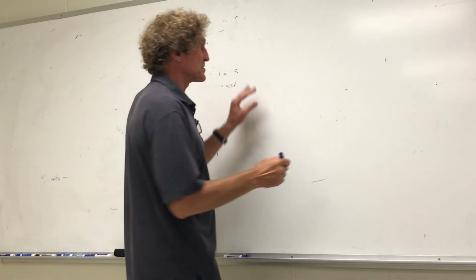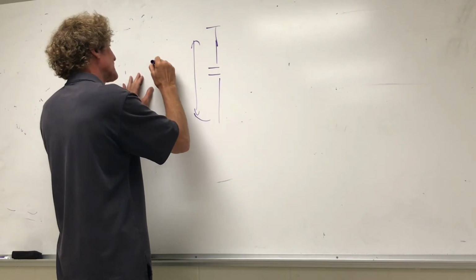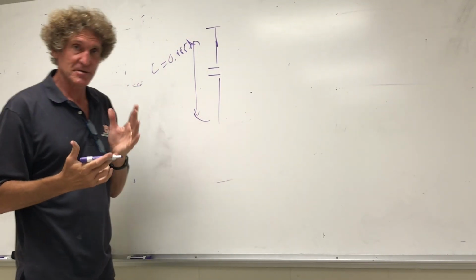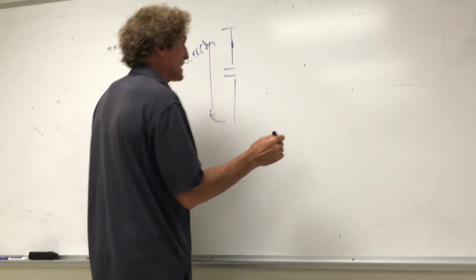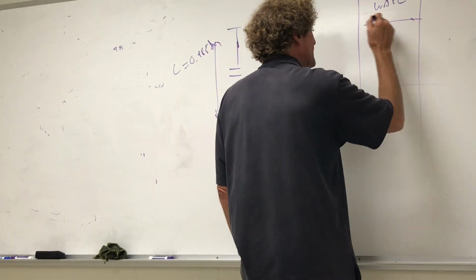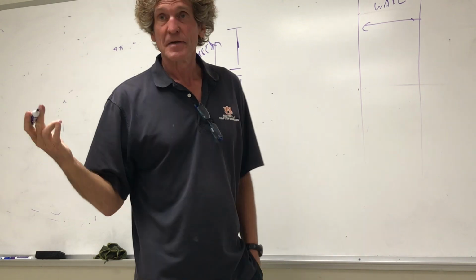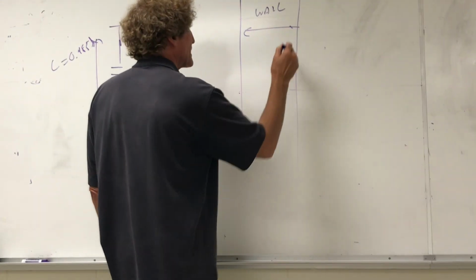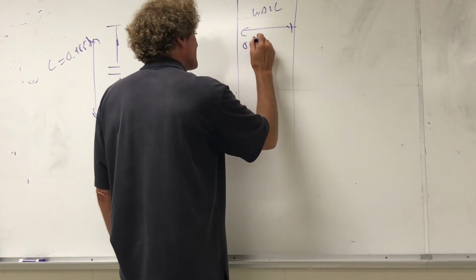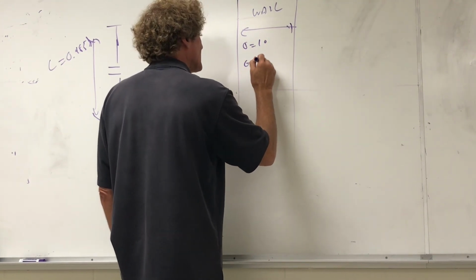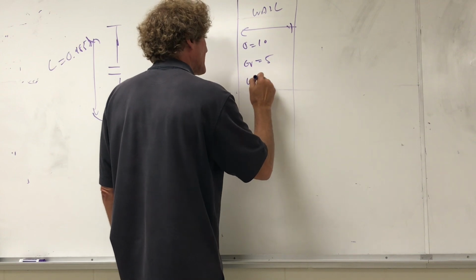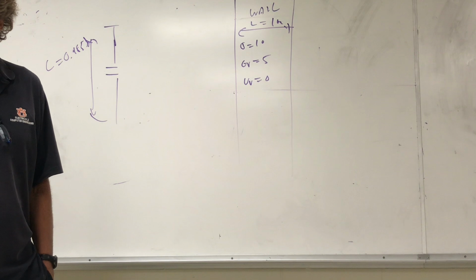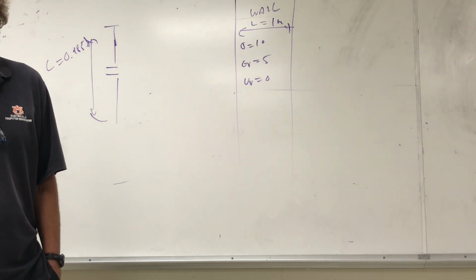All right. Suppose I have a dipole antenna with a length of 0.485 lambda. I don't want to make this hard. I'm trying to just show you. Then I have a wall. Now, electrically model the wall. Let's make it real simple. Suppose the wall has sigma of 10, epsilon relative of 5, and mu relative equals 1. Make the wall 1 meter thick. That's probably an oversimplification, but it'll work for proof of concept.